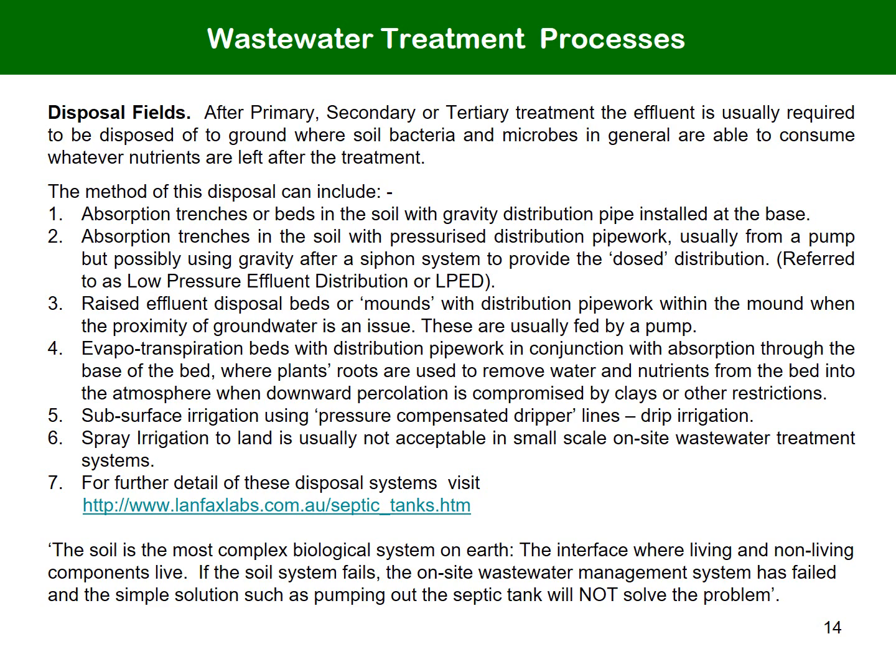Subsurface irrigation uses pressure-compensated dripper lines, drip irrigation. Spray irrigation to land is usually not acceptable in small-scale on-site wastewater treatment systems.